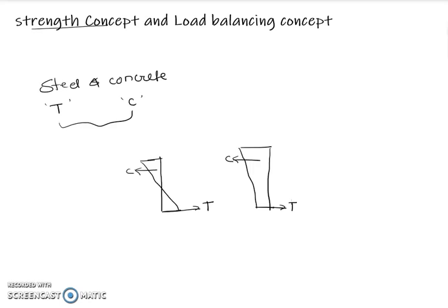Now let us see what is load balancing concept. Here in this particular concept, pre-stressing is achieved by load balancing. Now what do you understand by load balancing? The load that is coming onto the structure is well balanced by the tendon that is provided within the structure. This concept was developed by a person called Lin.